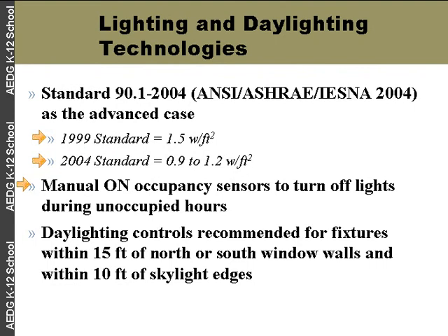And this is very advantageous, especially in areas where you do have daylight into the room, even though you're not necessarily counting on daylight for energy savings. Why walk into a room that you're immediately going to turn around in and have that occupancy sensor automatically turn the lights on? So you have to hit the switch basically to turn the light on, but after you leave, then it will automatically turn the lights off.